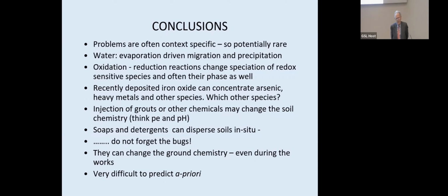And the problem there, looking at organic coatings, was that things like tanks, water tanks, not Ukraine type tanks, can be coated with sort of plastics and various lining materials. And when you probe the suppliers of these materials, they say, well, generally we can't really give you much guidance beyond about 20 years, and you're looking for 120 years, because most of the structures to which our products are put, like say a tank on a ship or something like that, have a working life of about 20 years.